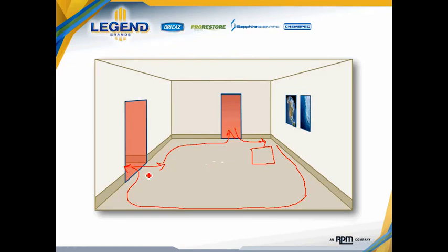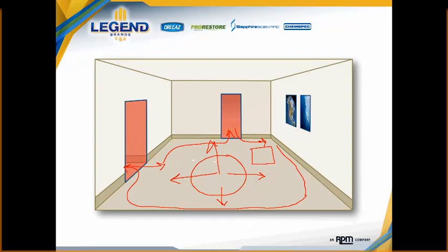Then once this perimeter flow has been set in this direction, the last piece here that we discussed is ensuring that we do the same thing by covering the center of the floor out here in the middle of the room. Again, axial air movement to generate airflow from the center out is the best way to achieve this, especially when the reason why we're having a challenge with air movement out here in the center of the room isn't just because it's a large open area, but maybe out here in the middle we've got lots of contents.